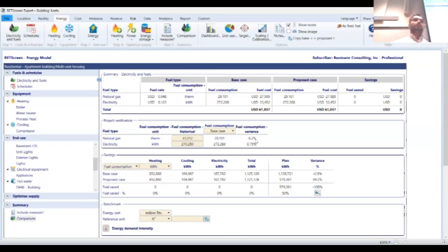If you come across a situation where the model is more than plus minus 10% off, that is a place where you need to do the calibration. The first step of calibration is to look at any place where you have made an assumption, vary it, and ensure that the model is within plus minus 10% variance. So this is where we have completed the baseline model and created a virtual model.